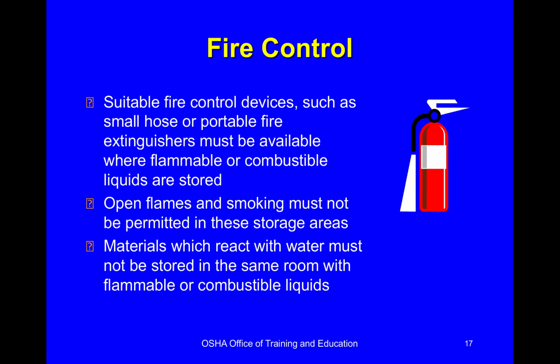Fire control devices must be present. Suitable fire control devices such as small hose or portable fire extinguishers must be available where flammable or combustible liquids are stored. Open flames and smoking must not be permitted in these storage areas. Materials which react to water must not be stored in the same room with flammable or combustible liquids.